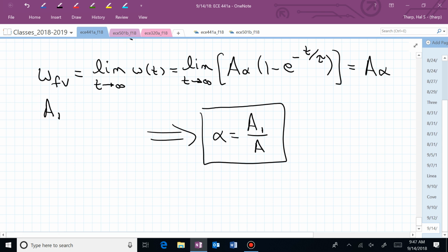Now what? So now we have one of the two parameters. Which parameter do we have? Now with this information, could you answer some questions that somebody might supply you? They say, oh, I put in 4 volts. What's my final velocity? Now you know how to calculate it because you've got the DC gain. You can't tell them how quick you get there. You don't know tau yet.